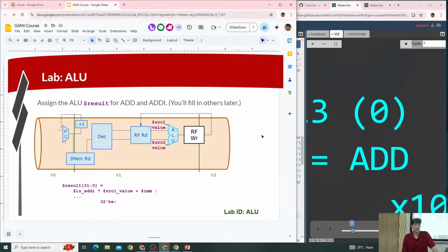Yeah, you can have multi-driven buses in Verilog that default to a Z value, and you should have one and only one driver of that bus, at most one driver. If there are no drivers, it would hold the Z value. Regardless of Verilog or TL-Verilog, we tend not to use that design style anymore because it's hard for the tools to analyze. But in the rare cases when you do want that structure, you can still use the Verilog assignment constructs in TL-Verilog. We're going to avoid that.